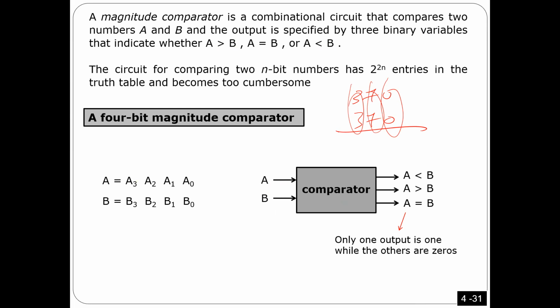You will see something interesting here, similar to what I did with the multiplier. I'm going to break the problem down into bits, as you will see right now. It's the same thing. If you have a number A, assuming this number is 4 bits, and a number B, also 4 bits, how can I know if these two numbers are equal or not? For these two numbers to be equal, these two have to be equal, these two have to be equal, these two, and these two.